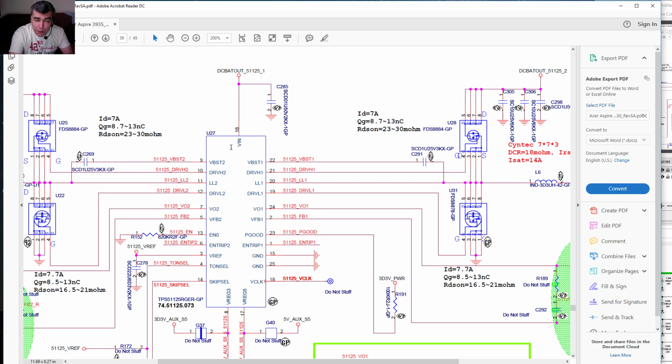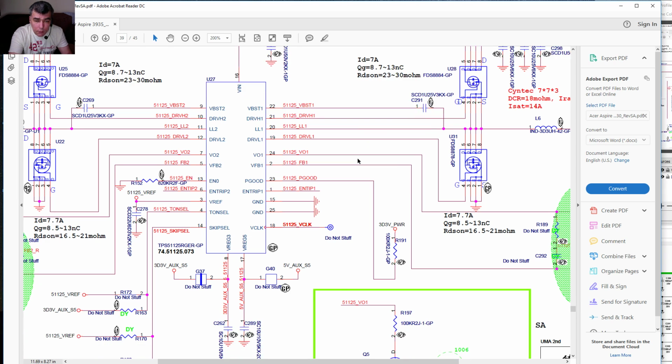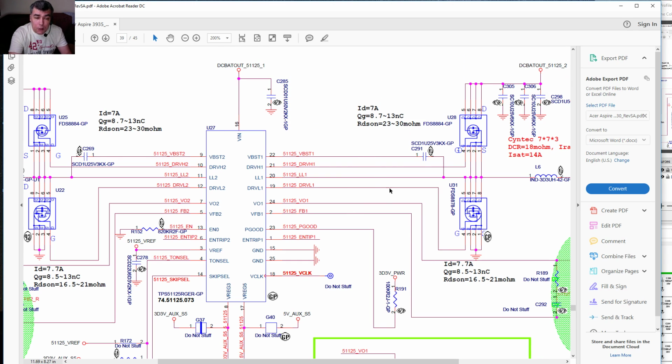If you have voltage on the chip, you can check each chip, you don't need schematics. You check each pin and see if you can find 19 volts. If you have 19 volts but no output, probably the chip is dead. You should have 19 on all the power supplies, even if the laptop is off.